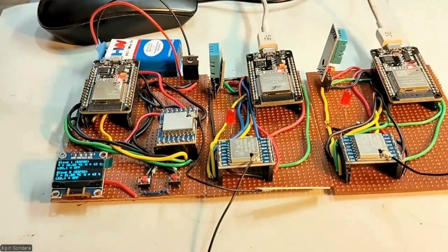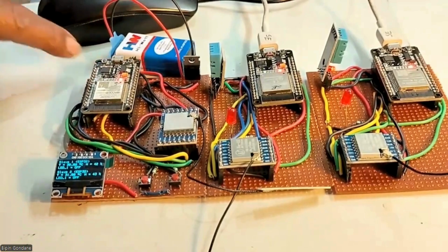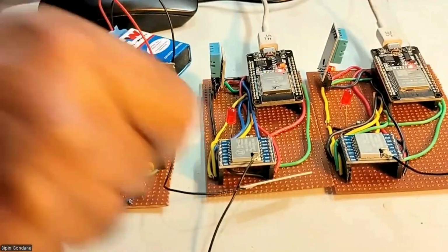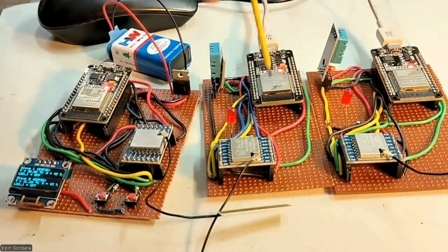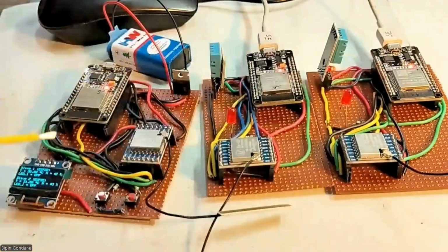Of course, I will give you the complete details about the project and the schematic diagram. It comes in the category of mini as well as major project. With this, you can come up with very good ideas. Please remember, the master I have powered through a battery. This is very important: a 9-volt battery and a 5-volt regulator. I have connected this. This is the master. For the slaves, I can connect the regulator here and give the connection. But since I have taken the 5 volts from my computer, you have to remember that.